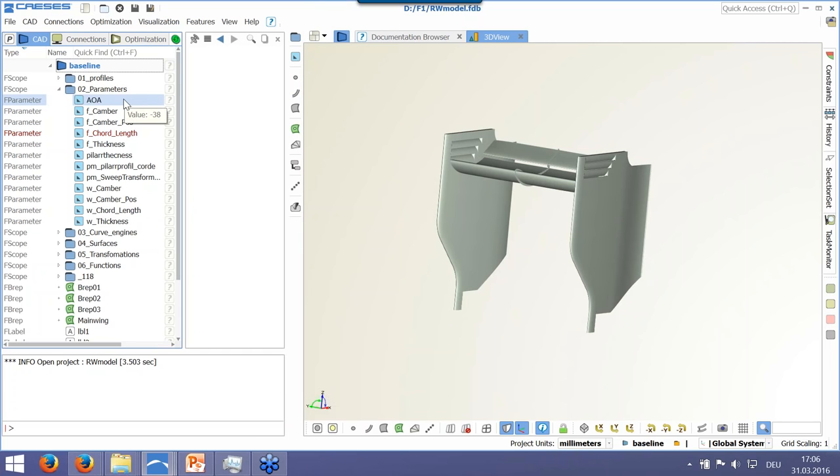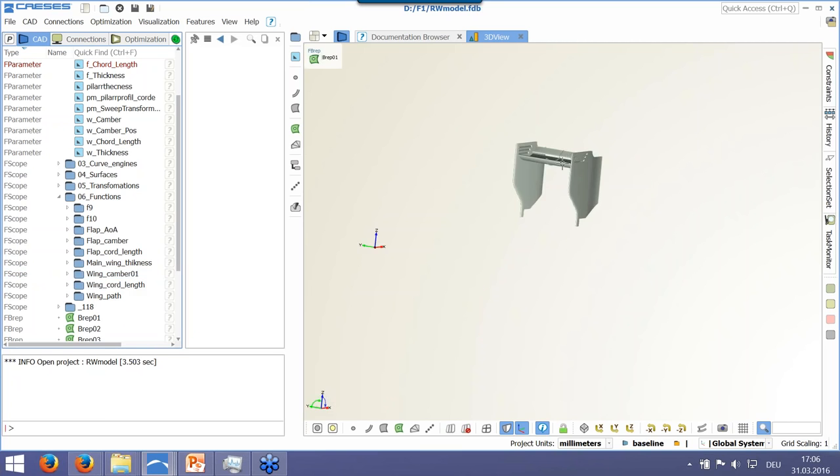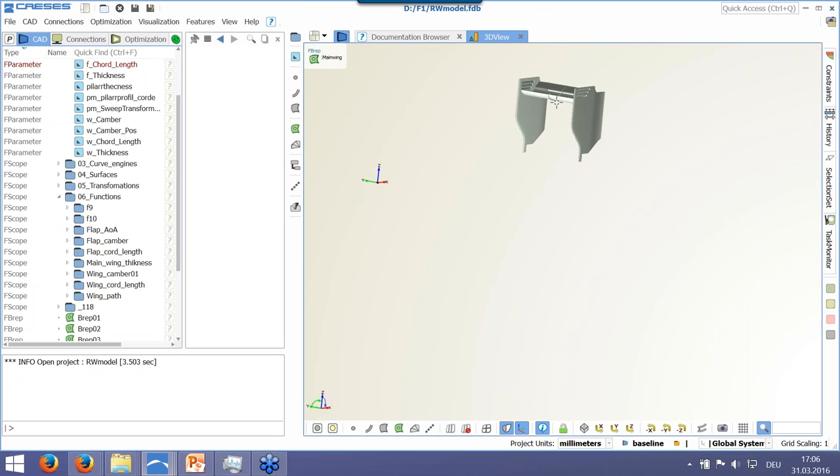And also, like I have said before, this technique of the meta surface, because this wing is created using the meta surface, so these parameters here are connected to these functions. So here we have functions, so for the wing chord length, every parameter from these ones here in the top is described by these functions. I mean described along the span-wise of the wing using these functions, and I will show you now these functions. Okay, so this is really important I think for you, because to do this later in your assignment.